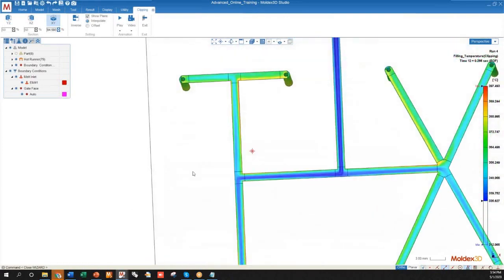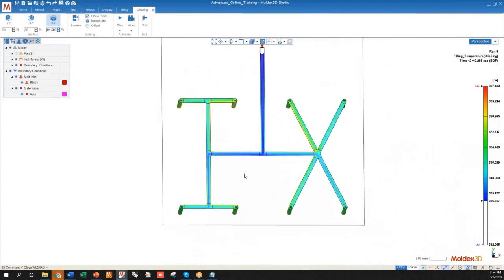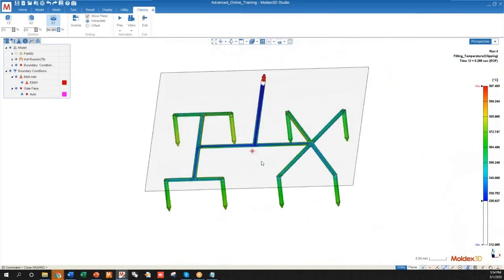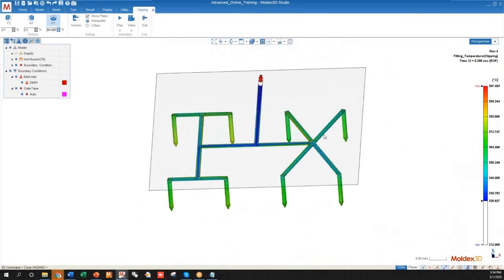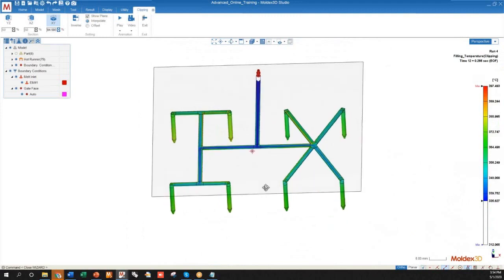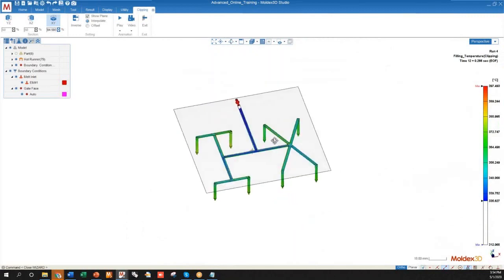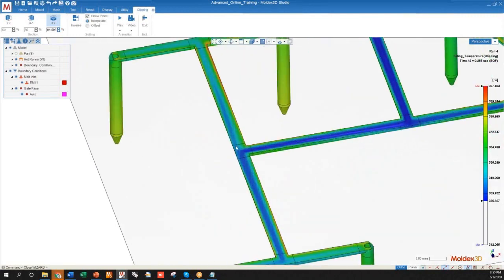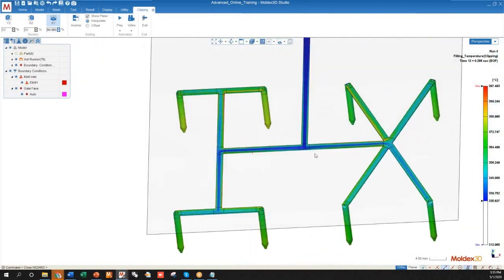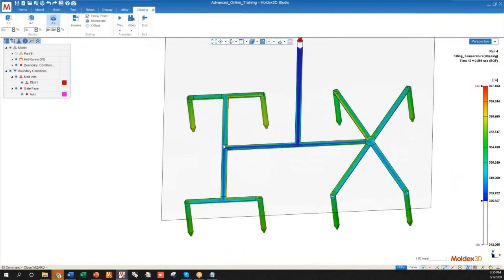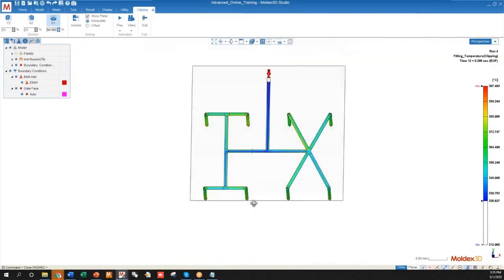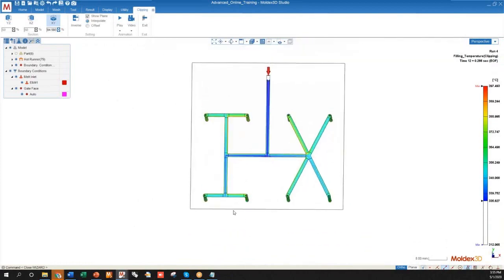But this shear heating problem is going to be apparent whether you use a line-defined or a geometry system. Both should be able to pick this phenomenon up. But the most important thing is that we're using the 3D solid mesh elements to calculate what's actually going on, rather than creating some junction assumptions, or just assuming that the melt flow creates some sort of pressure drop. We actually want to see what's actually happening with a 3D solid mesh.